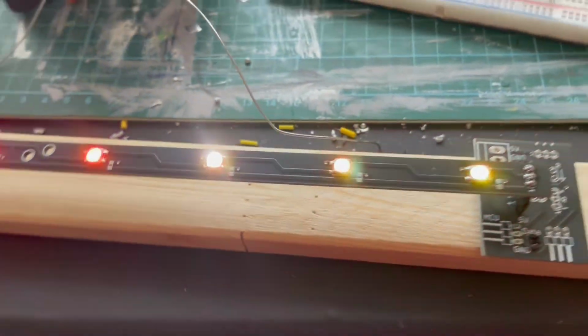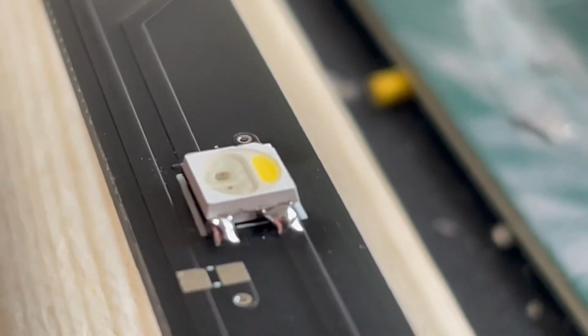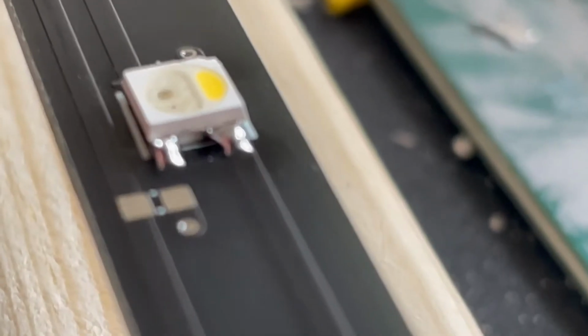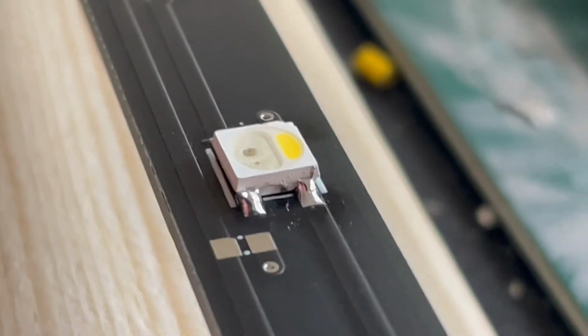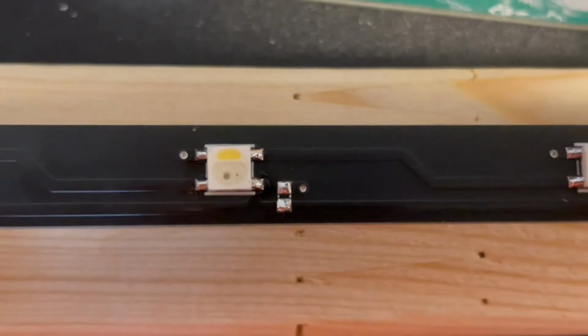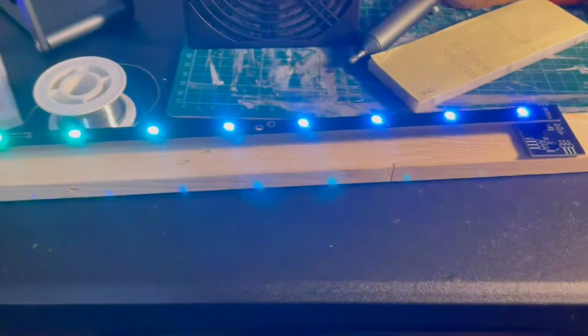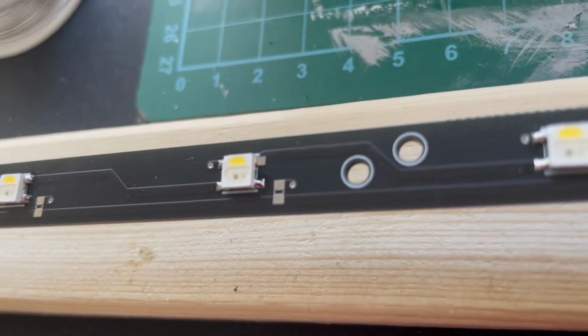Along the way there were some soldering issues. For example, I would frequently put too much solder on where it would overlap a small metal piece, keeping the white component on. Reflowing and removing some of the solder fixed it. When soldering and testing the remaining strips, I also managed to solder a short on one of the capacitor pads, which was easily removed, and luckily, the LEDs were fine. There we go. Sometimes I even forgot to solder some pads.